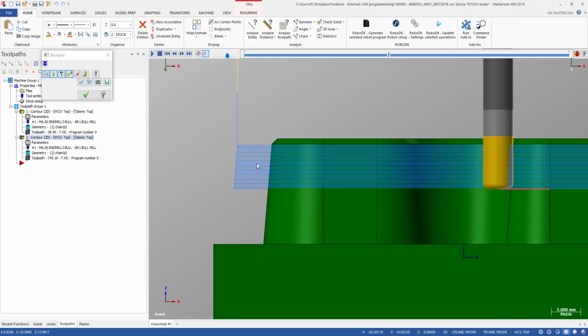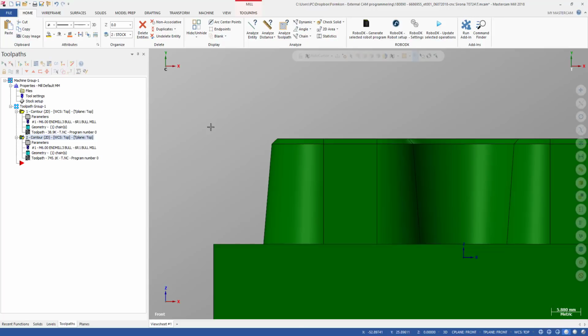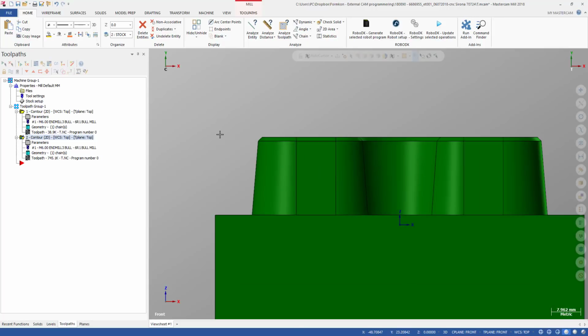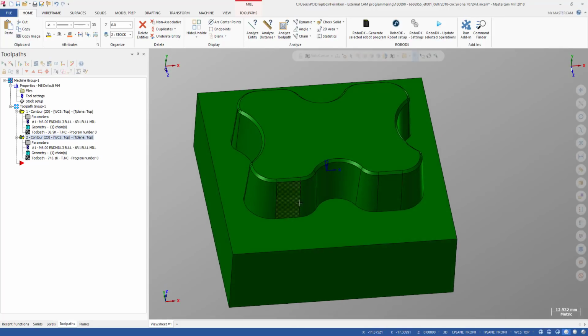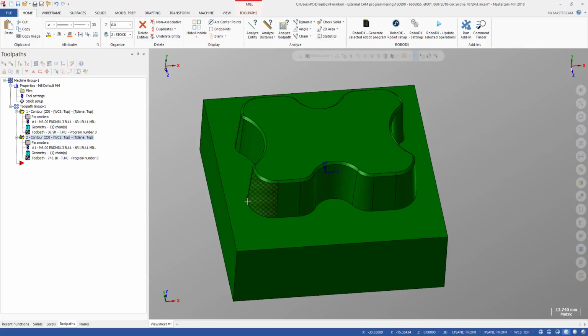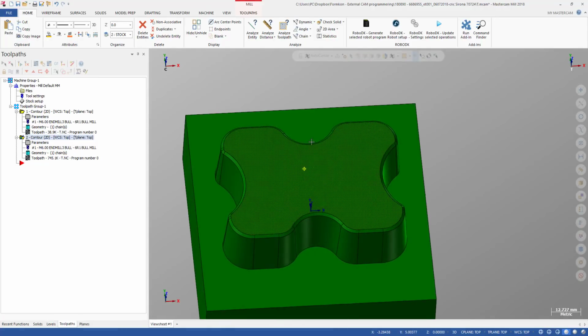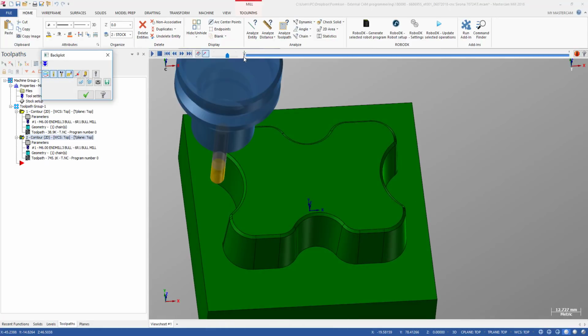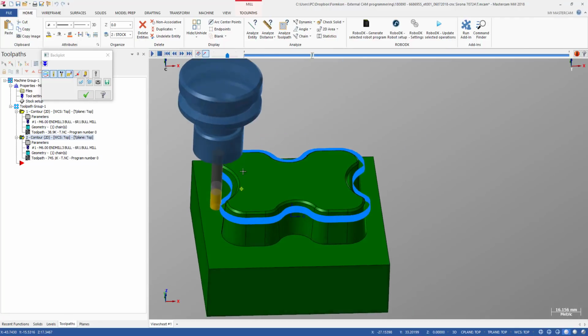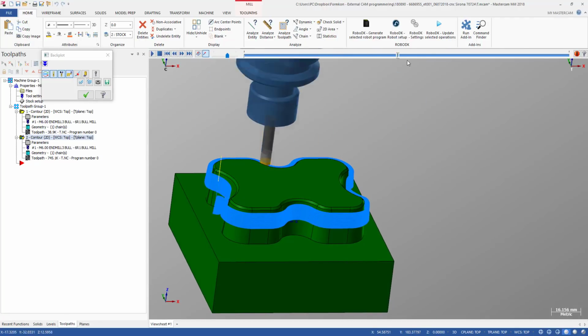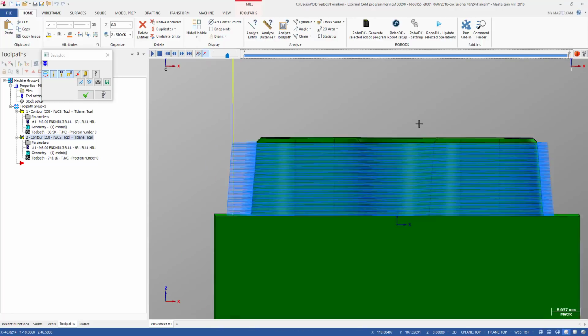Yes, it's very powerful, but you know what, because we can only input one value of the taper angle, if this part had a variable taper angle, it will not work. This tip can only work on a part with constant taper angle. Yeah, that's the limit of this trick, but I think this is good enough for a lot of surfaces.